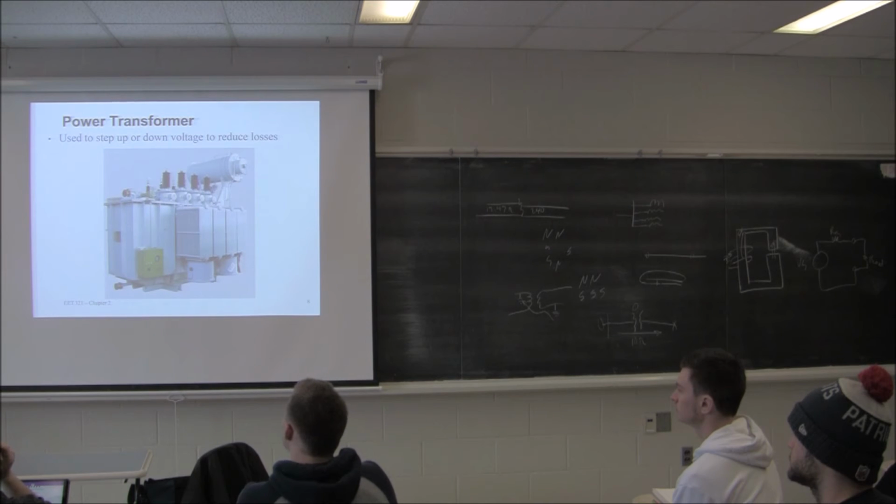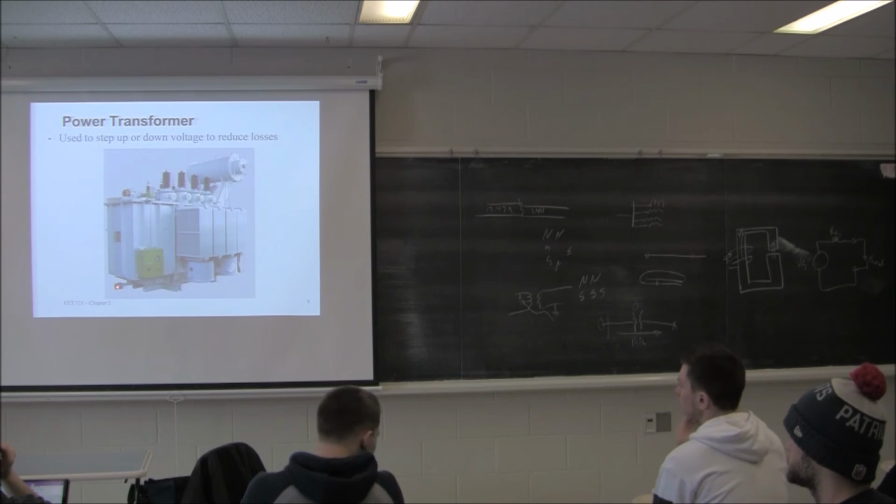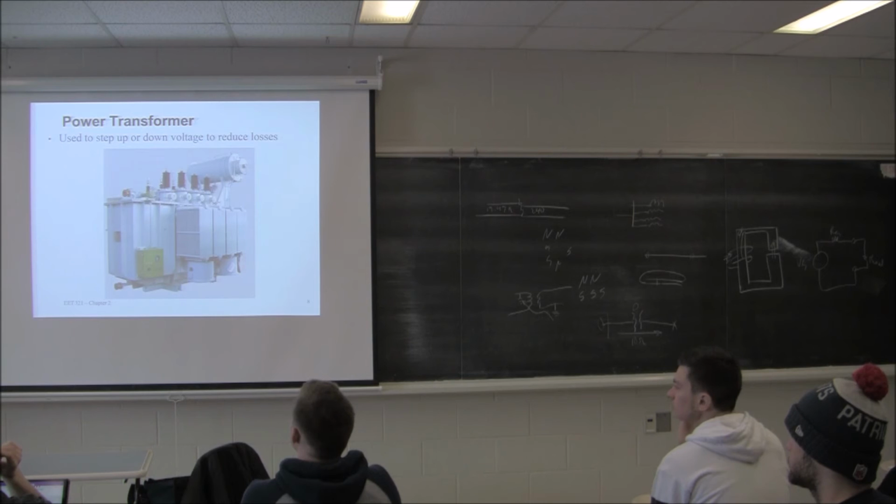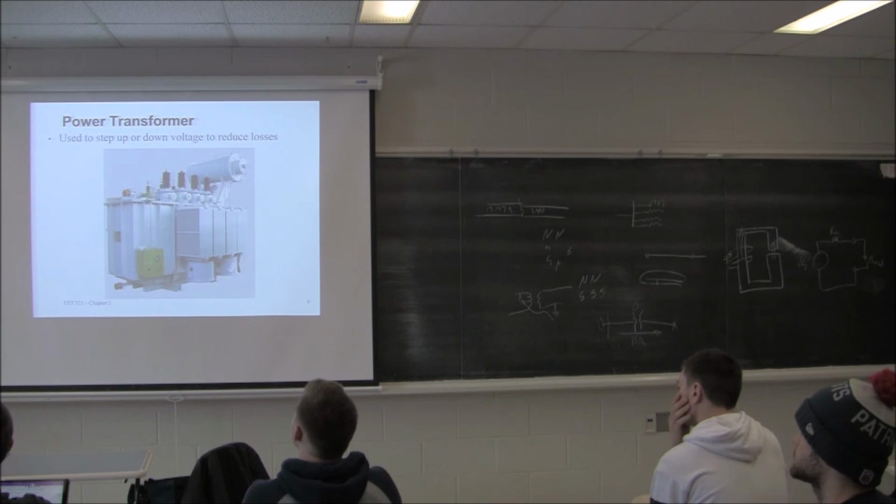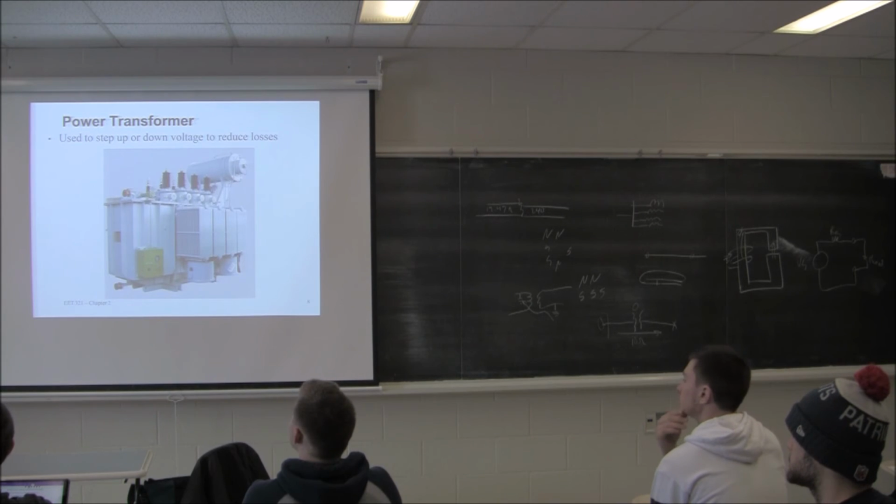That's a possibility. It's not very often, but you can see here you've got a drain and a fill. And actually, these transformers are pretty heavy. They're always shipped empty, right? Because you're limited to what, 100,000 pounds on a trailer? Doesn't take long with some oil to get to 100,000 pounds. So these are always shipped under vacuum. Well, actually under slightly positive pressure, again with nitrogen.